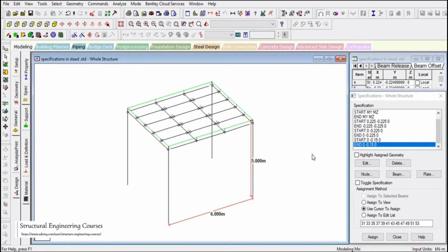There's one more thing that I'd like to add here, because in structural steel members we also have bracings. So how we can add the brace is that we can just left click on add beam, and left click here, and then left click here again. So similarly we need to model bracing from this point to this point.